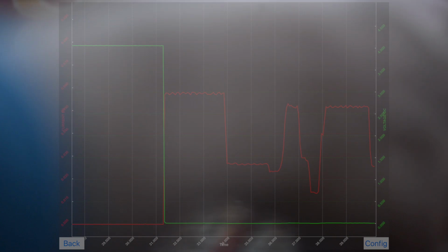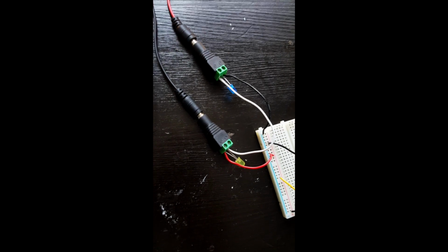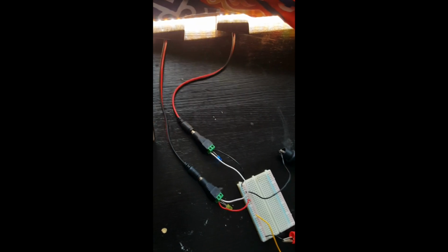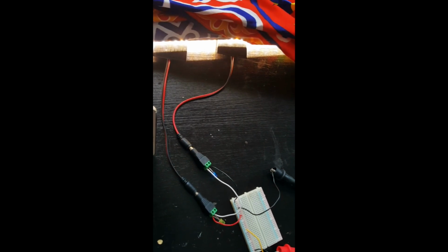And as you can see, they're much better at shading because voltage is not as sensitive to light intensity as current is. Okay, so we're back to a series configuration, but this time I have these LEDs across each generator, which are acting as bypass diodes. And the reason why I'm using LEDs is if they're working, we're going to see them light up. So the bypass diodes are there to short any negative voltage, or to really short any current that the cell that it's shorting can't derive for itself.